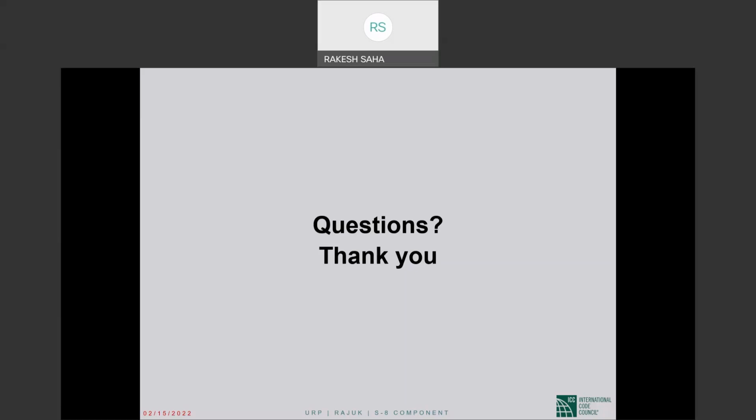Is it required to check the serviceability limits for dynamic analysis again when we are satisfied our structure in the ELF method? We talked about drift check.